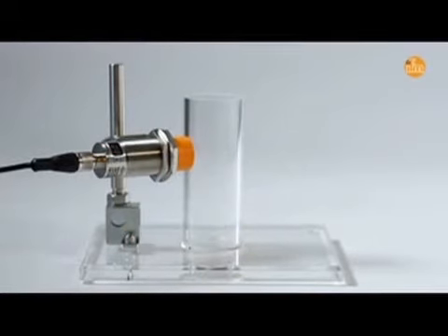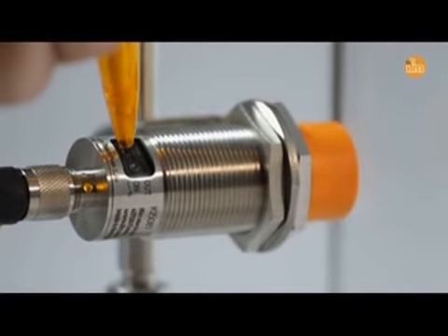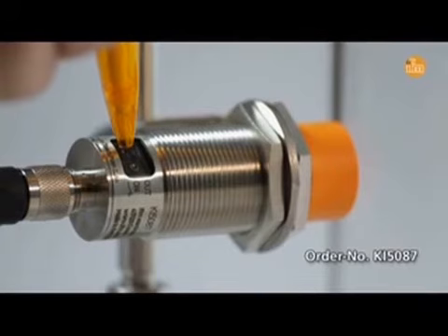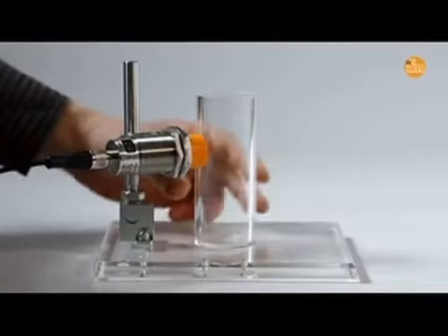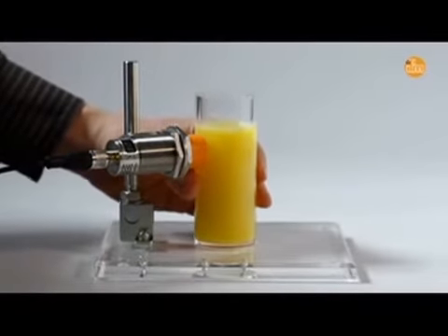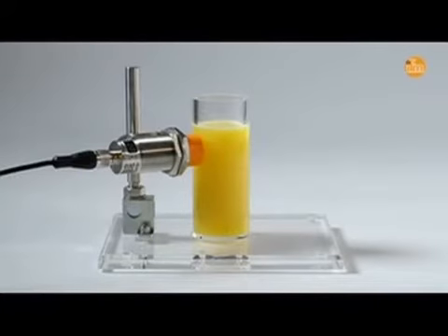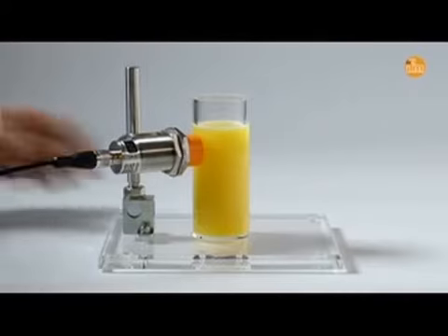Okay, first of all, we are going to have a capacitive sensor and an empty vessel. Then, by adjusting to the empty state, the sensor suppresses the installation surroundings and reads the sensor. After that, take the empty vessel and fill it with some orange juice. If the level rises above the set value, the sensor will be switched on. But if the level is below the set value, the sensor switches off.